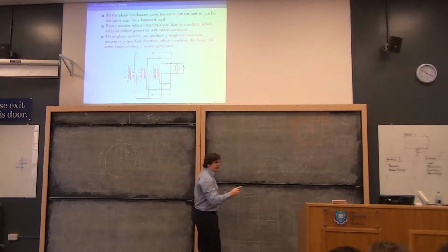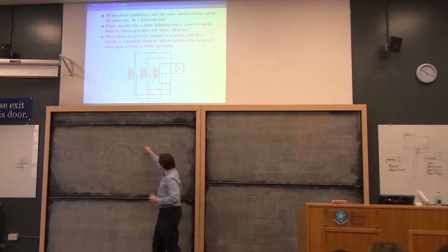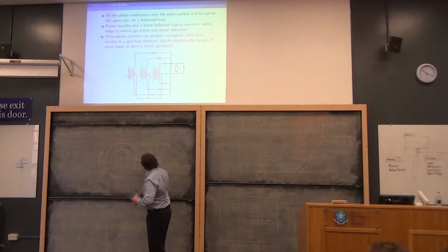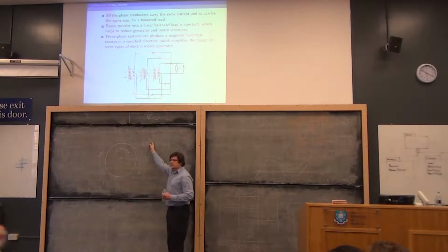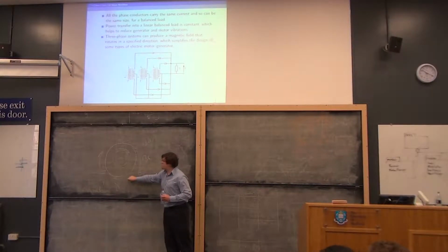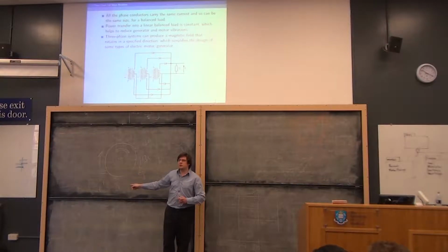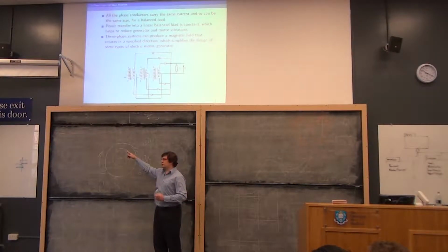Having the phases spaced 120 degrees apart, if I call this one the brown phase, the black phase is here and the grey phase is there, this phase is 120 degrees ahead of this phase, and this phase is 120 degrees behind that phase. So this one, then that one, then that one. If I put brown down here again, without any effort at all, I've got currents which are in the order that I want to make it look like the magnetic field moves. So if you observe it over time, you'll say, well, the field is moving.